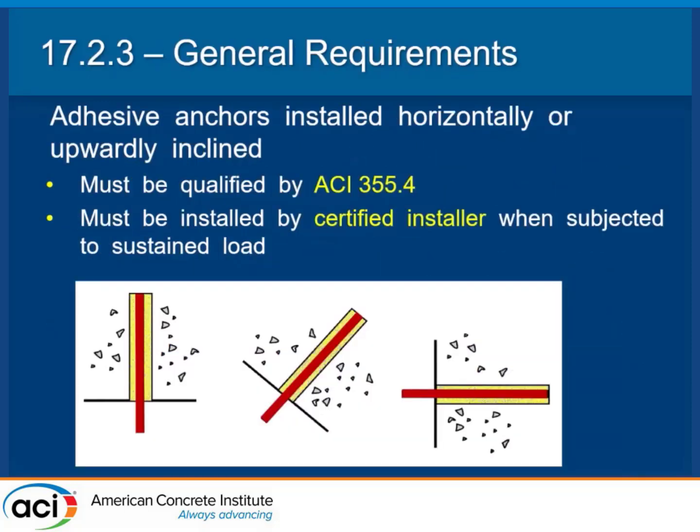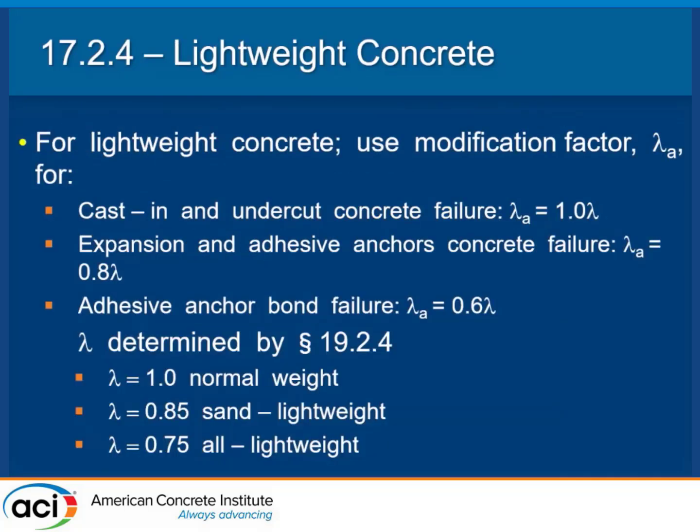And as I said earlier, for adhesive anchors that are installed horizontally, upwardly inclined, or overhead, they always have to be qualified by 355.4, and you have to have a certified installer.